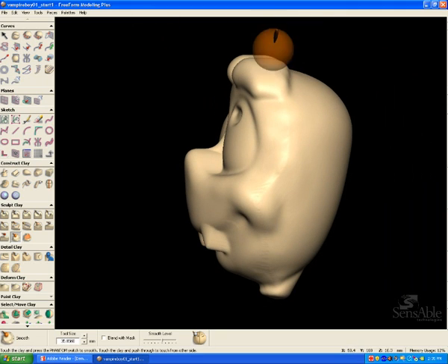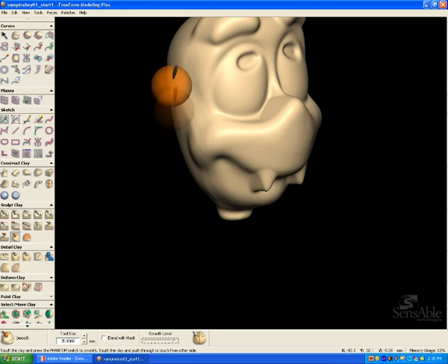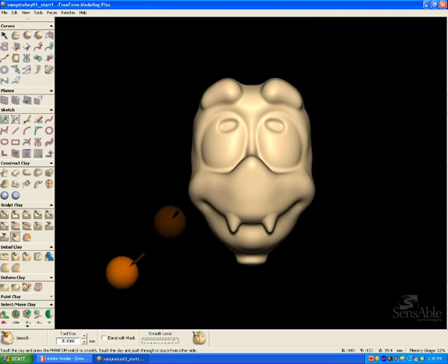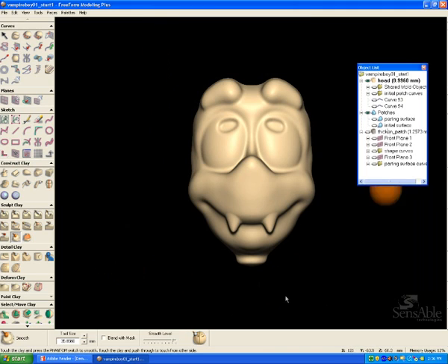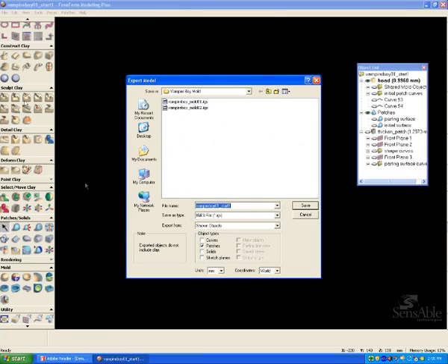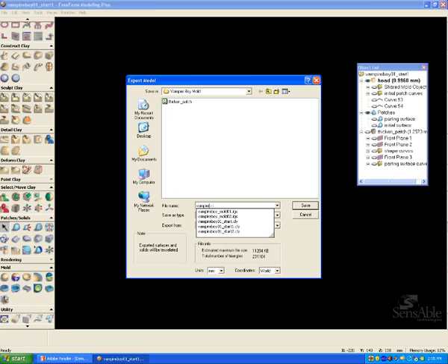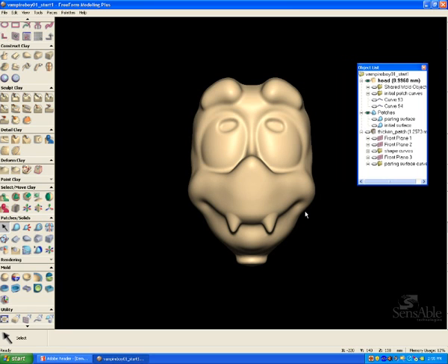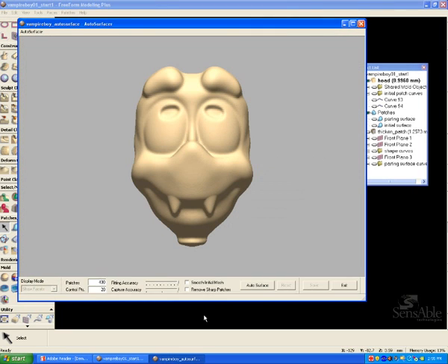what will become the two parts of the mold that I will be creating actually in Rhino once I export the parting surface that I've created. So now that I've cleaned that up, I can go ahead and auto surface my figurine head, and I'm going to export this to our auto surfacer, which is only available in FreeForm Modeling Plus.